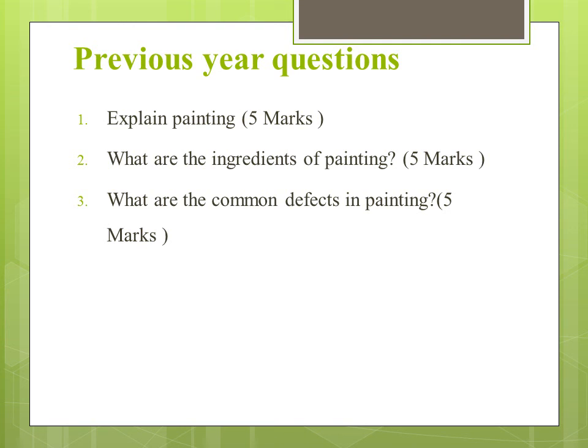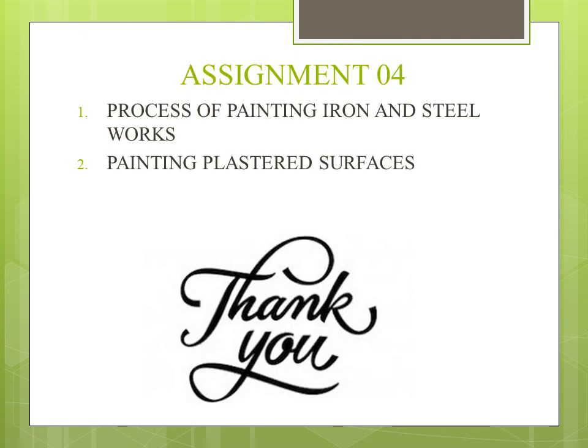The 6 ingredients, that is the base, carrier, extender, pigment, solvent, and dryer. What are the common defects in painting that we discussed at the last? Blistering, blooming, flaking, flashing, grinning, running, wrinkling, and saponification. These are the previous year questions.